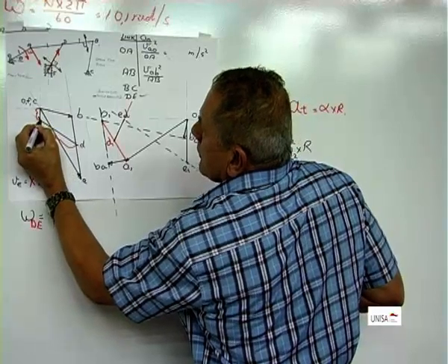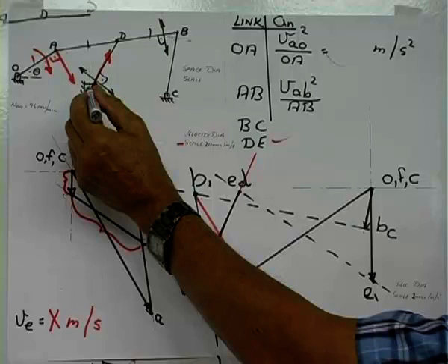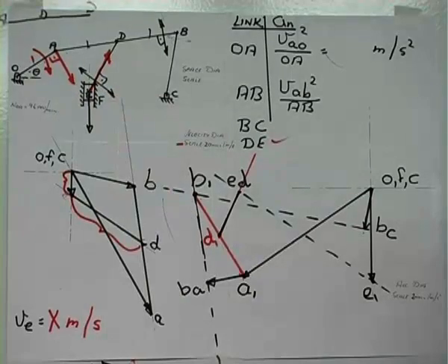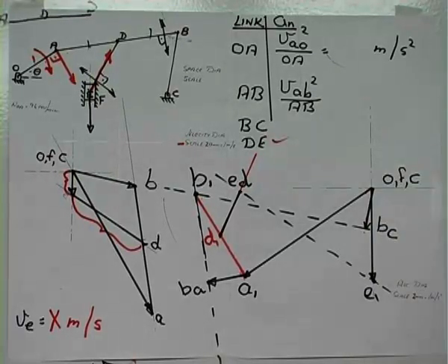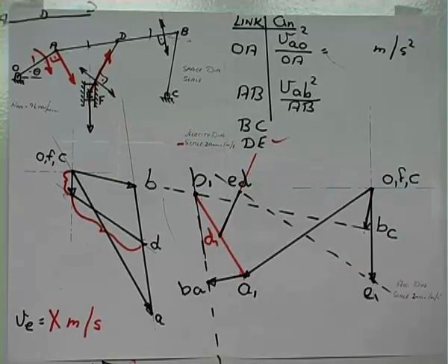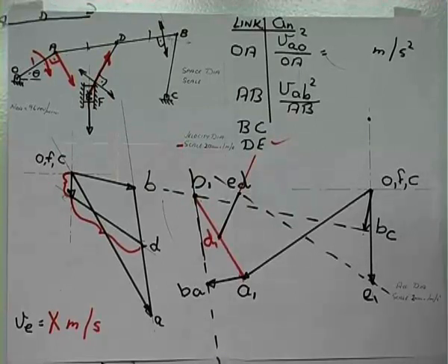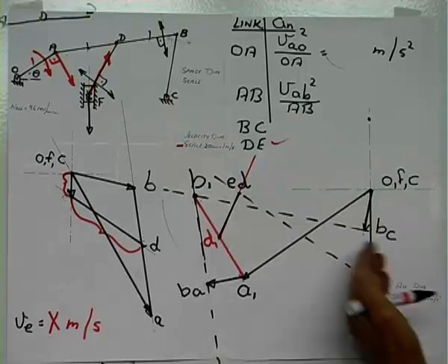For your velocity diagram, always from your fixed point, as you can see here, will be the direction. So according to this, for this moment, E is moving vertical down. Also with your acceleration diagram, you can see it means E is accelerating vertical down. If you do a construction and you get E in the opposite direction, it only means it decelerates and not accelerates. And from here you can do your calculations for your angular acceleration.